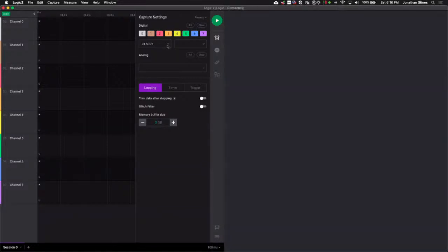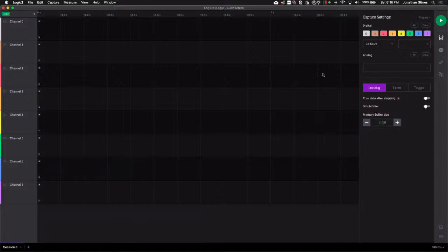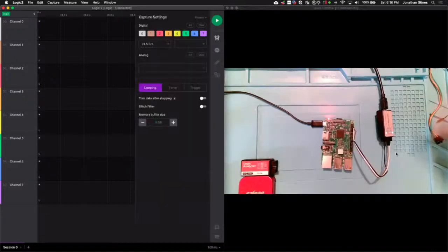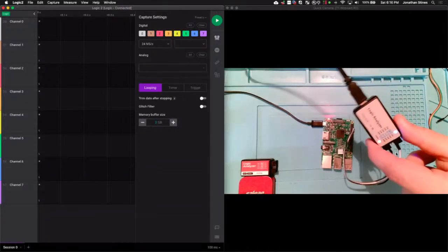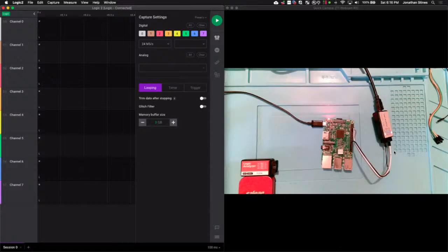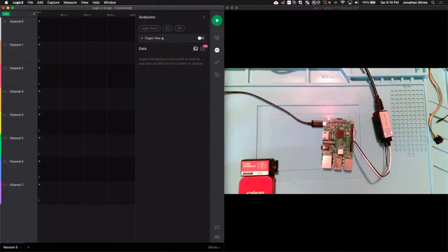Just to give you the quick rundown, I'm sorry for shifting this screen around, but remember, we still have the cheaper-end logic analyzer hooked up. We're about to switch over to Saleae though. I want to show you guys some other stuff. So this is the new Saleae Logic 2 software. We're now at 2, and you can change the amount of channels that are hooked up here. You can change the different protocol analyzers associated with the connections that you're making.